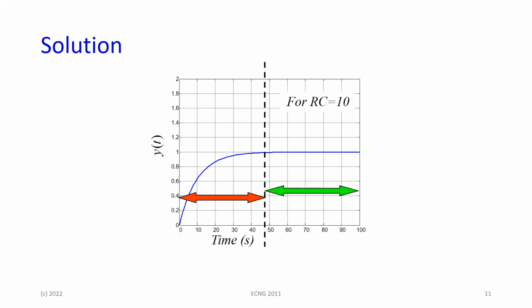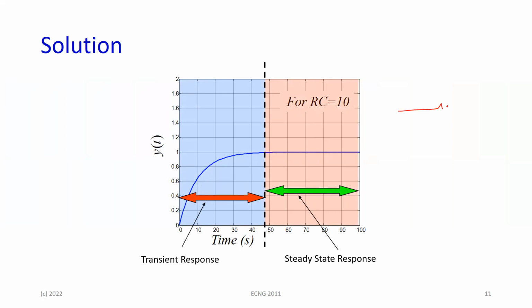And as you can see, the step response now has a couple of parts to it. There's a part where the value of the voltage, or the output of the capacitor, remember, it's this again. So we're looking at the voltage here. Once I put this step voltage in here, for a while, depending on the value of R and C, the voltage, of course, this is a sudden change.